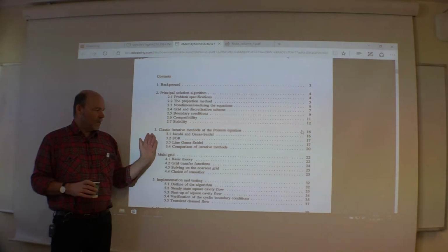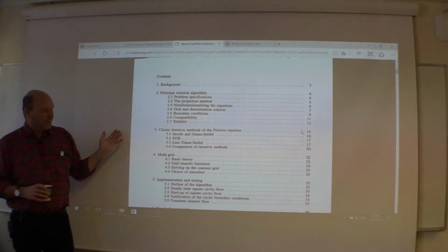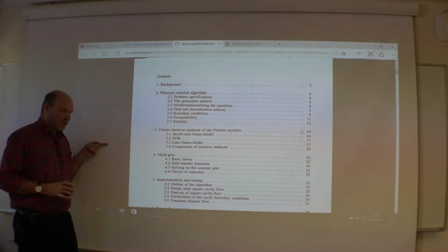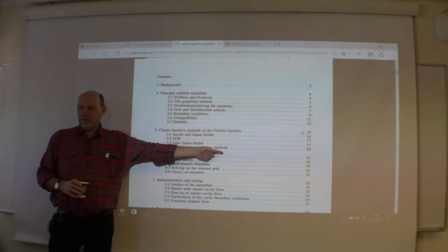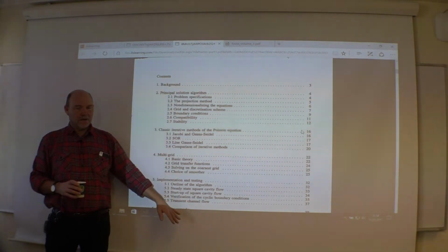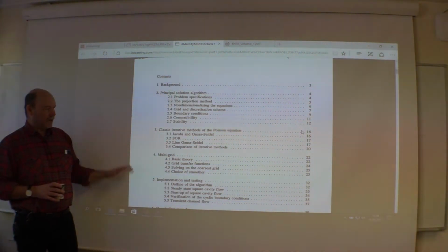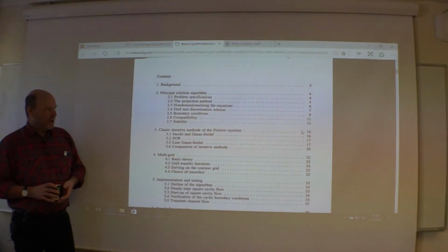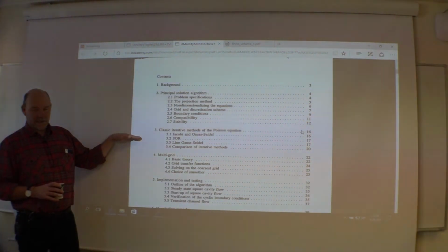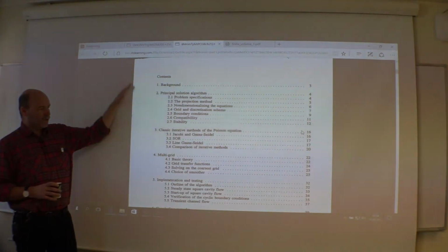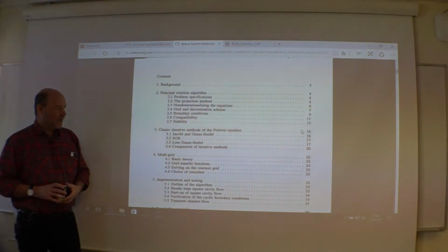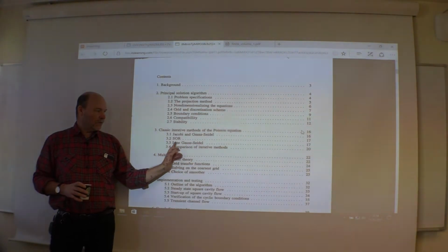If you take a 2-dimensional or even a 3-dimensional case, and then you say along one single line, I have my unknown, straight through the domain, only along that line. Everything else I assume is known. Then you can write your equation system as a 3-diagonal system and solve it directly. Then of course you have to take the next line and the next one and sweep across the entire domain. So that is what a line solver is.